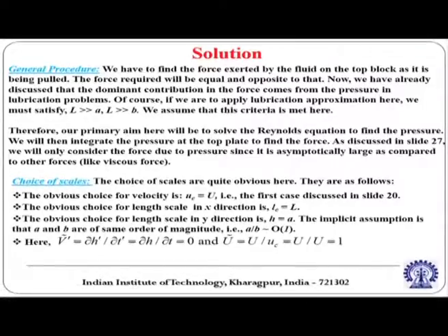The force required will be equal and opposite to that. So, this is basically Newton's third law type of thing. So, basically we have to find out the force distribution on the top plate, force exerted by fluid on the plate. We have already discussed that the dominant contribution in the force comes from pressure in lubrication problems, unless you have additional body force that comes into the picture, but here we have not considered any other body